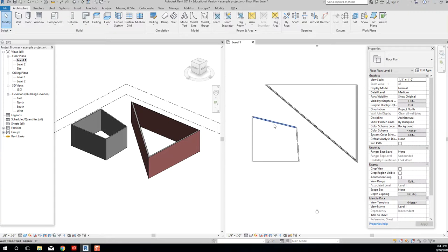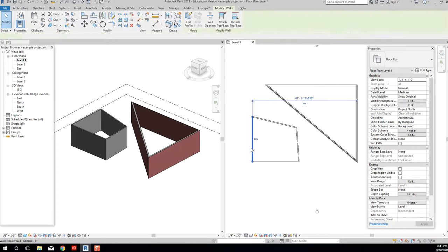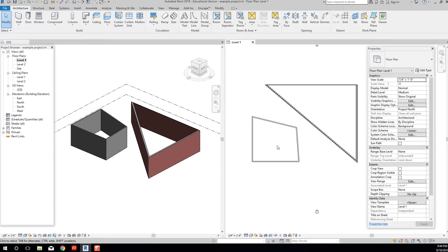When I'm in a floor plan view, I pick, but I can also see that selection in 3D, right? I can go over here, click, and I get all these selections happening in 3D as well. I want to remind you this is a 3D model. So even though I'm looking at it in floor plan view, it still exists as a three-dimensional object. So if I pick something in floor plan, that object also exists in 3D. Remember that all these things are interconnected. It's a good thing to learn early: if you delete something in one spot, it deletes it everywhere.